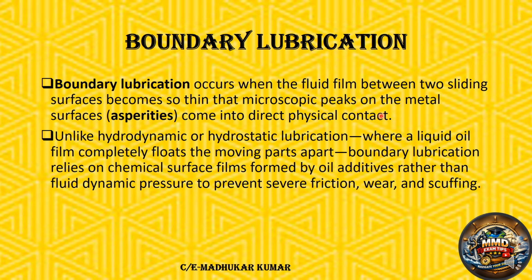Unlike hydrodynamic or hydrostatic lubrication, where the lube oil film completely floats between the moving parts, in case of hydrodynamic and hydrostatic, due to the oil pressure, it is separated. Boundary lubrication relies on the chemical surface film formed by the oil additives, rather than fluid dynamic pressure, to prevent severe friction, wear, and scuffing. So it is a different concept altogether. The lubrication happens, the separation happens, but some of the microscopic peaks are in contact.